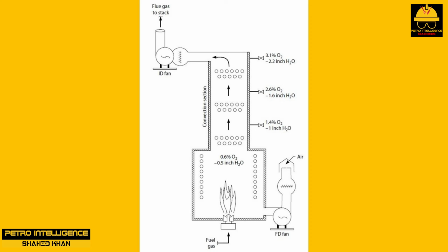The convective section flue gases then cool and shrink, re-establishing a negative pressure as before, and, as before, air leaks into the convective section. The hot, unburned hydrocarbons from the firebox mix with that tramp air and reignite in the convective section. This cycle of events will continue, except each time the ambient hydrocarbons ignite in the convective section and the pressure changes from negative to positive, the leaks will increase in size as the boiler fabric is shaken.